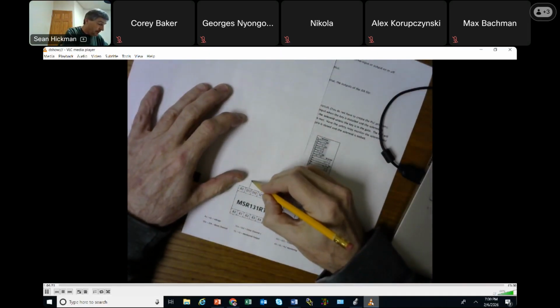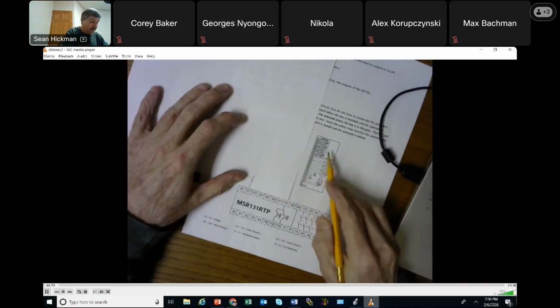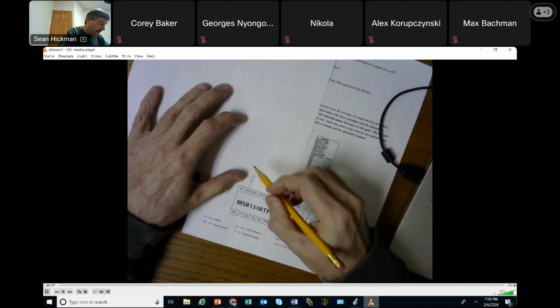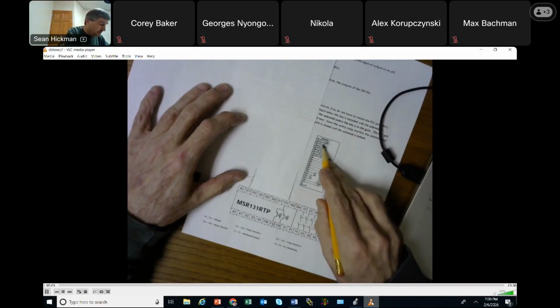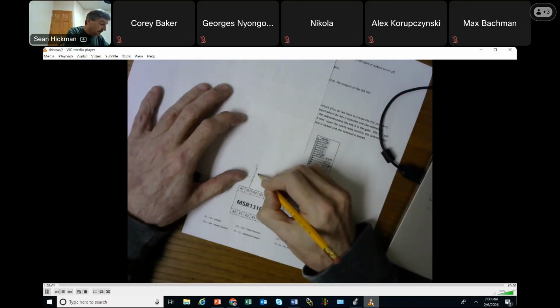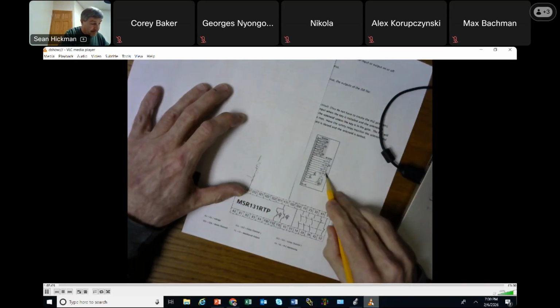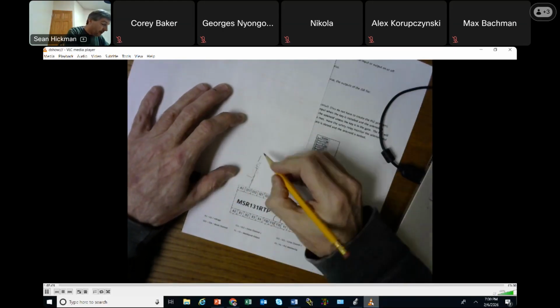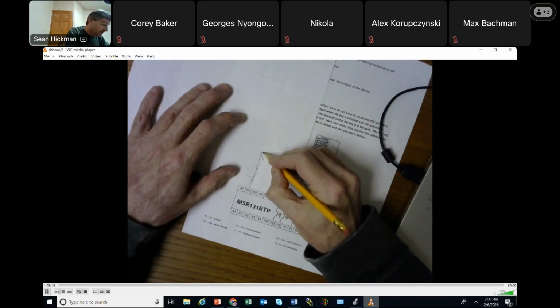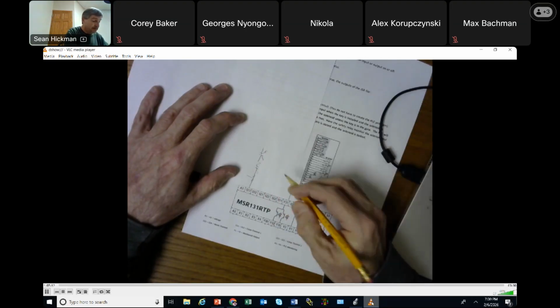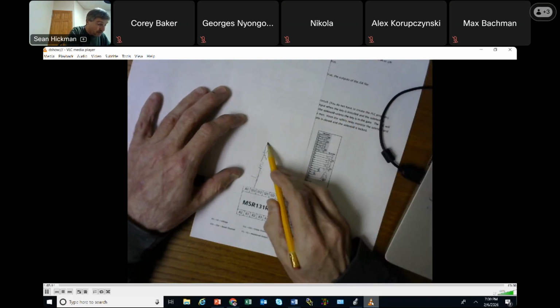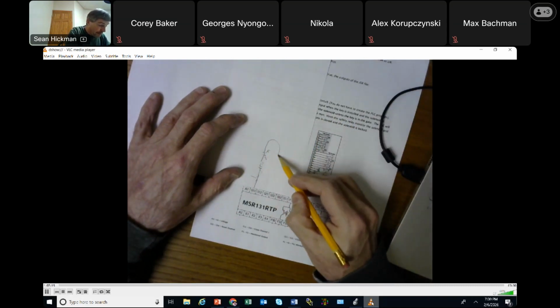So you're probably putting an E-stop, and then it said use one of the safety gates here, which you could do 11 and 12 there. And then maybe it had to be locked, so you're using 21 and 22 here. It'd be open, sorry. And then it could run whatever. And that's running then back to here.